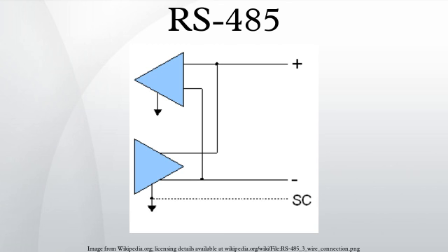Standard scope and definition: RS-485 only specifies electrical characteristics of the generator and the receiver. It does not specify or recommend any communications protocol, only the physical layer. Other standards define the protocols for communication over an RS-485 link. The foreword to the standard recommends the Telecommunications Systems Bulletin TSB-89, which contains application guidelines, including data signaling rate versus cable length, stub length, and configurations.